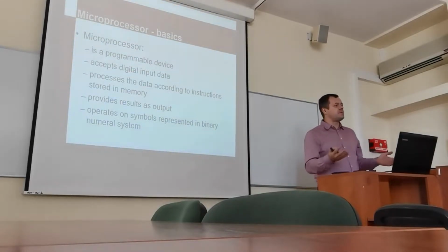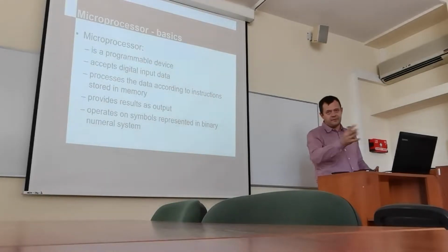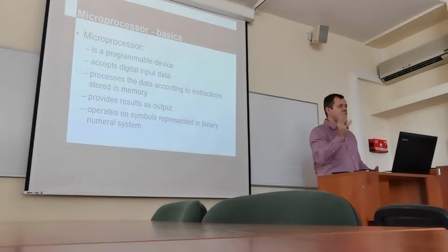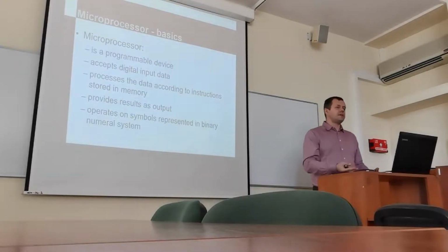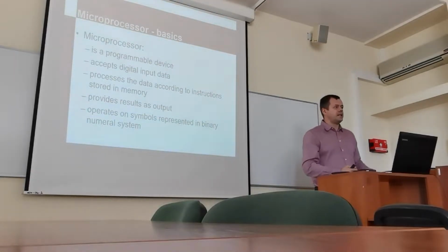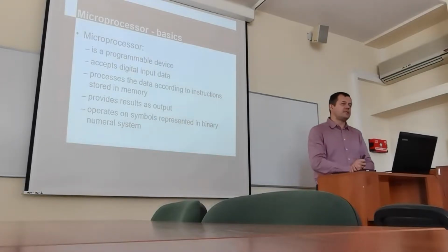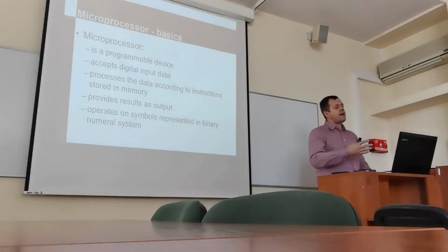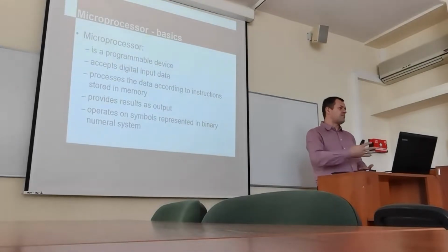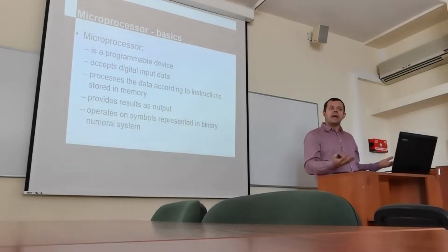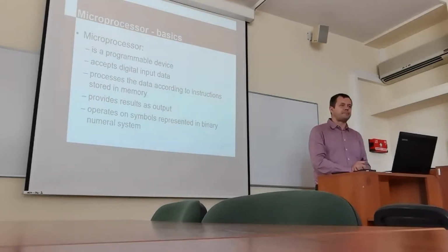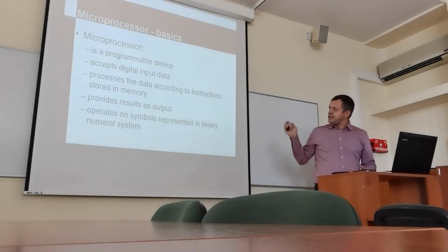Because the FSMD, the classic FSMD, has a fixed functionality. So it's a finite state machine with data path, so we have a data path, we have a finite state machine, but the finite state machine has a behavior which is fixed. Here, in case of microcontroller, the only difference in fact is, and that's what I was showing during the last lecture, previous semester, we have a stream of data, we have a program following, changing the finite state machine, changing the behavior of the finite state machine. So that's why it's programmable.